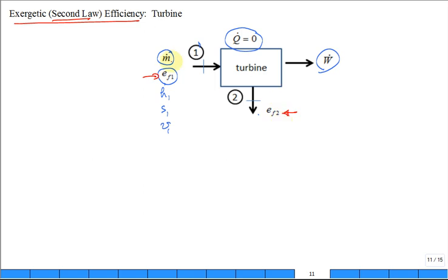The turbine has only one M dot, true? You think this is steady state? Sure, it's steady state. Turbine operating under steady state conditions. Okay, no accumulation or depletion of mass in the control volume. Now, what we were interested in is a review. We had isentropic efficiency before, did we not?